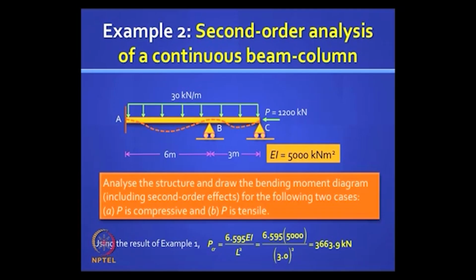You will get a good feel of it now. If you can do the conventional slope deflection method which we studied, but that cannot account for the reduction in flexural stiffness due to the axial compression, right. Now we will take two cases, one axial compression of a fairly high magnitude. Obviously that axial compression should not exceed your buckling load. So first you calculate the buckling load.